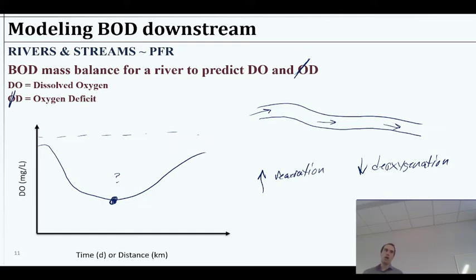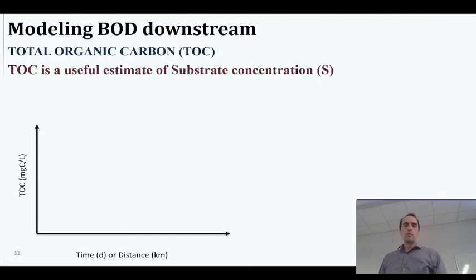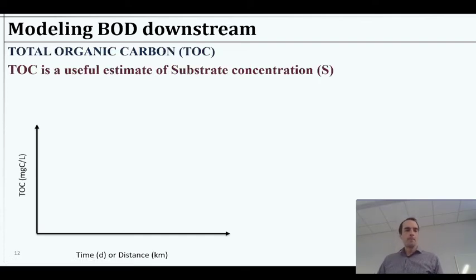So are we completely depriving the stream of oxygen, or is it just 6 milligrams per liter of oxygen instead of 9? Because in that case, 6 milligrams per liter probably supports all fish and wildlife, right? So it's not a big deal. It will also be temperature dependent. So maybe we look at what happens during the summer versus the winter and things like that. The biological activity will also slow down when it's cold. So that could complicate things. Not that we're going to go there.